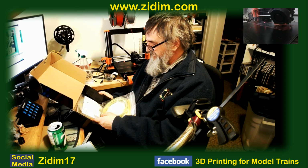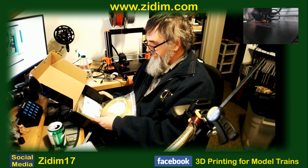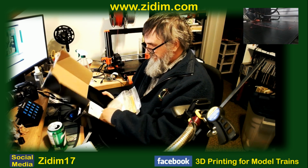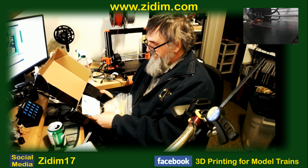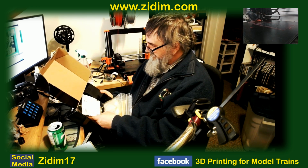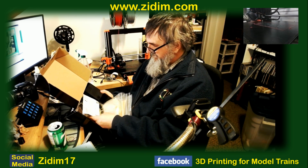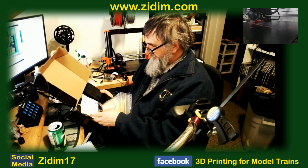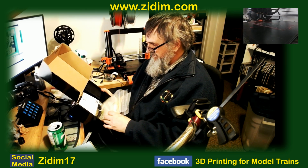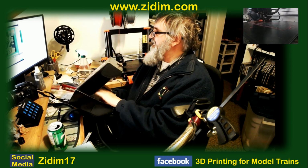Hot end temperature, 190 to 230 Celsius. And this is NatureWorks, by the way. And some PETG. 240 to 270. Whose company does it say? IC 3D Printers. Okay. Extensively tested, put through the paces, and they're all in a 3D printing service bureau. So some black PETG. So we'll put that to work as well.